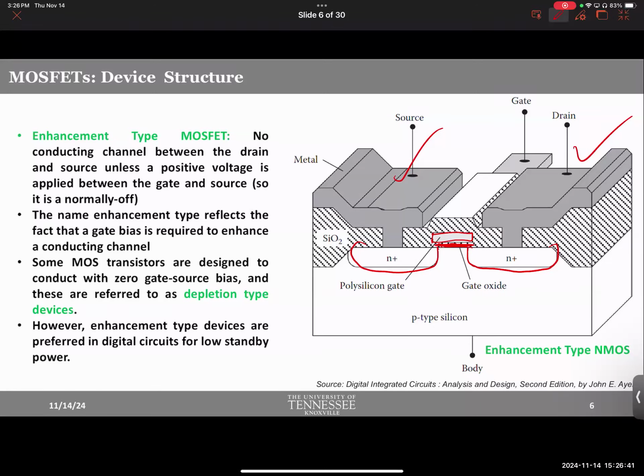Why? We had a separate lecture, and I actually deliberately added that lecture to this course because I think this is important. Heterojunction. Remember, there are two kinds of connection between metal and semiconductor: ohmic contact and Schottky contact. Schottky contact, you don't like. Ohmic contact is good, right? So how do you know that when you connect something to a semiconductor directly, it will be ohmic? No guarantee. There are so many considerations. Remember, right? Even if you don't remember, it's okay. But you know that that's a concern.